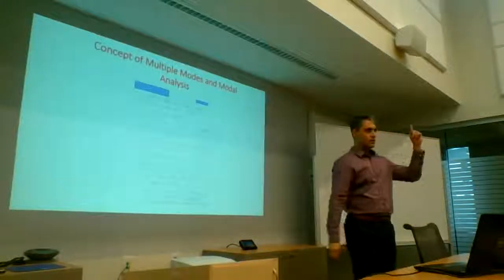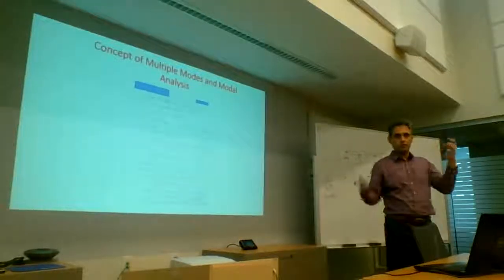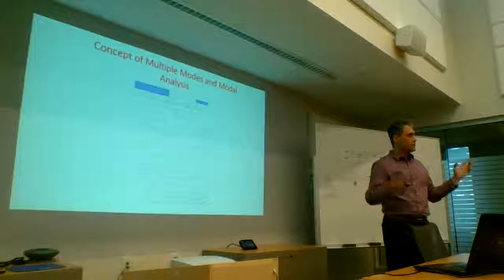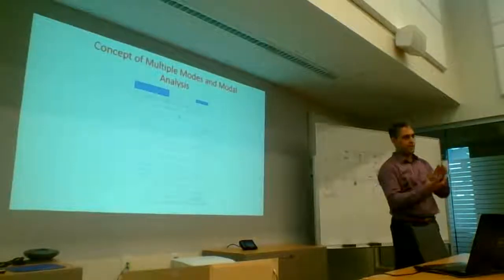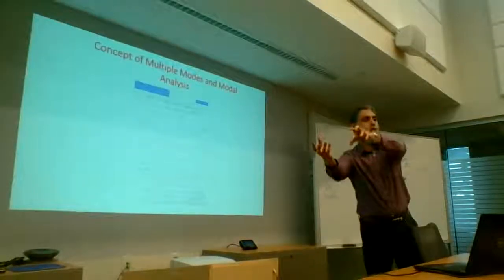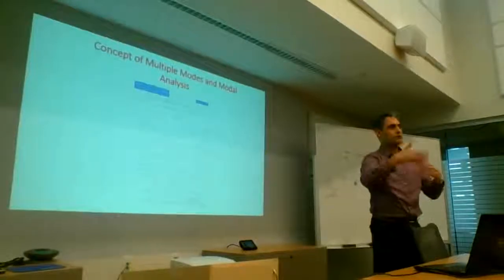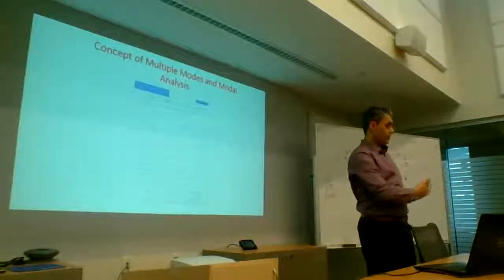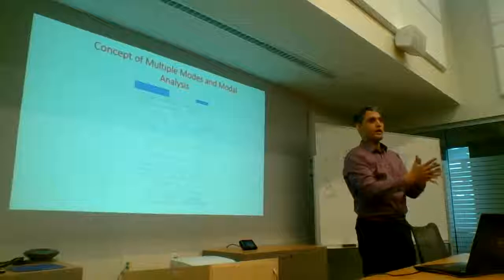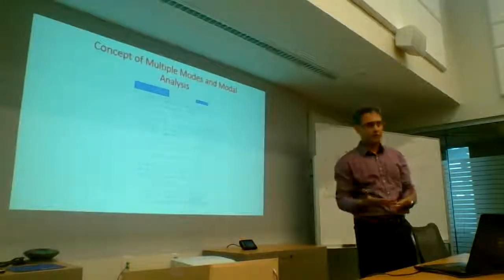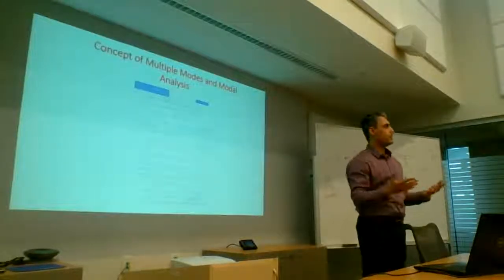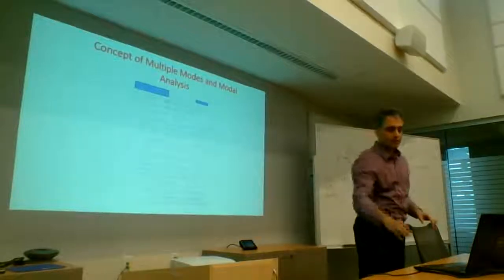And guess what? We've solved one equation before, which is a single degree of freedom system. So now this multiple degree of freedom system has been decomposed into many, many single degree of freedom systems. And you solve them separately, just like we solved the first one. And then you combine them, as I talked about, with the modal combination and the directional combination.